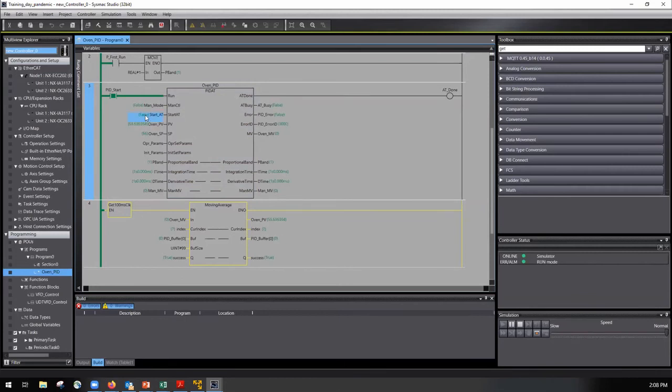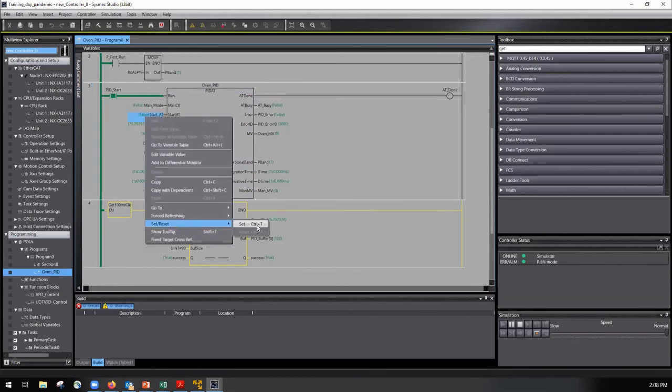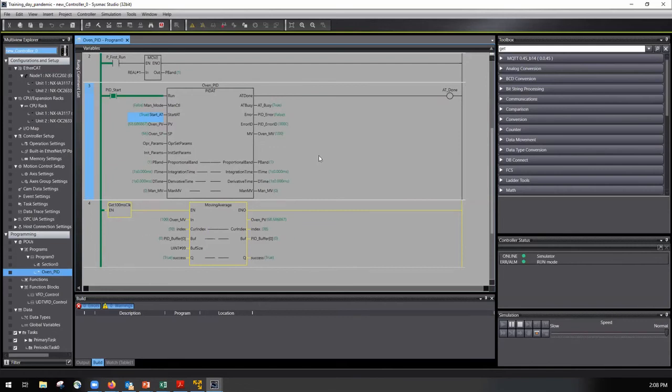And now I'm going to flip this bit true and let this, it'll jump around a little bit, but it was very quick in the simulator because my feedback loop was too perfect. It's not really real world conditions, but you can see all of my parameters now, my P band, my I time, my D time, they've all been tuned. They've got 60 milliseconds on my D time. I've got 1.4 seconds on my I time, and my proportional band has settled on 515.